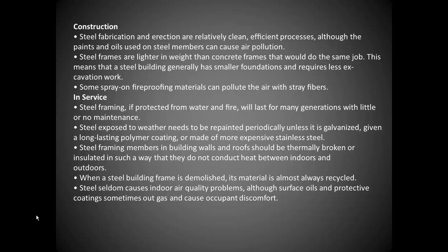Steel frame members and building walls and roofs should be thermally broken or insulated. And I just mentioned that about the steel building, that finding a way to put a thermal break between the outside and the inside of the steel is a good way to prevent heat loss, because it does transmit the cold so well. We remember my old school that had single pane windows, a lot of them still in the university.